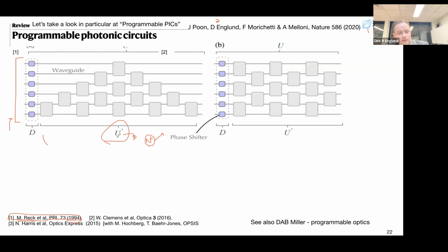Unitary transformation, linear optics, unitary transformation possible. They gave us a recipe. And here is that recipe. This is that recipe from these guys implemented now in what we would use in modern day photonic integrated circuits. And each of these blocks here is a Mach-Zehnder interferometer. So you have the input modes, output modes, and this is the so-called Reck-Zeilinger decomposition of an arbitrary unitary linear optics transformation.